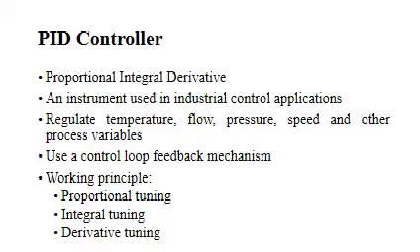For example, if an oven is cooler than required, the heat will be increased. Here are three steps. First, proportional tuning involves correcting a target proportional to the difference. Thus, the target value is never achieved because as the difference approaches zero, so too does the applied correction.